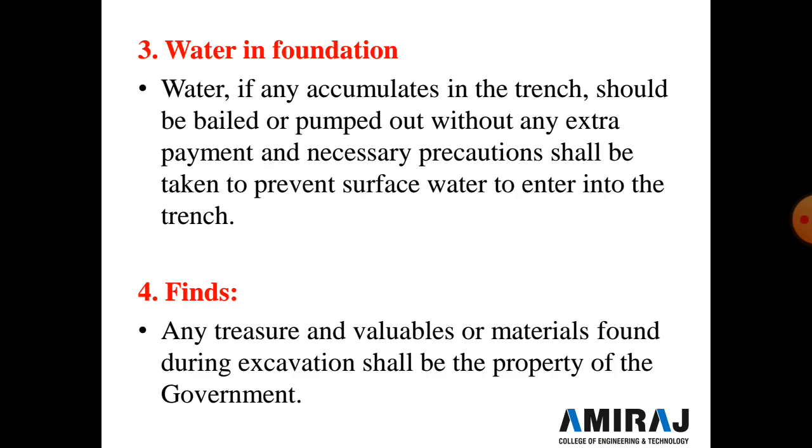Sometimes if the water table is high, we get water during the excavation time or during the foundation work time. So water, if any accumulated in the trench, should be bailed or pumped out without any extra payment, and necessary precautions shall be taken to prevent surface water from entering the trench. Now the fourth point is finds. Any treasure or valuable material found during the excavation shall be the property of the government.